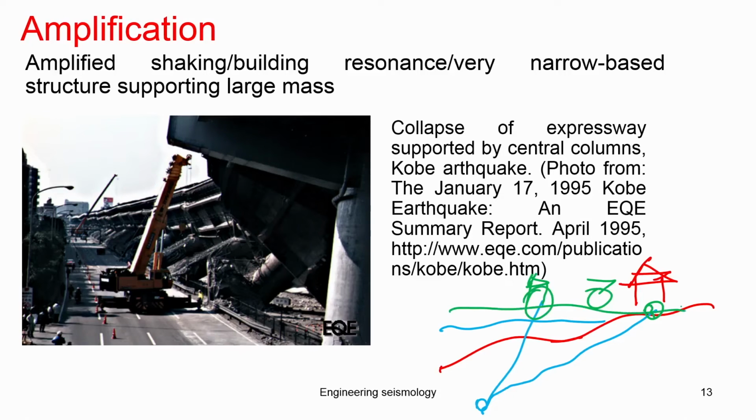So, you will get a different dynamic force or vibration level, which is what we have seen in the wave propagation theory. Particularly, some of the structures fail, and this will be the direct ground shaking hazard. This is due to the amplification of the waves in this portion. This is basically amplification due to the soil medium. Sometimes the structural configuration itself is not sufficiently designed to take the vibration, so that causes a failure. That kind of failure we call an amplification failure.